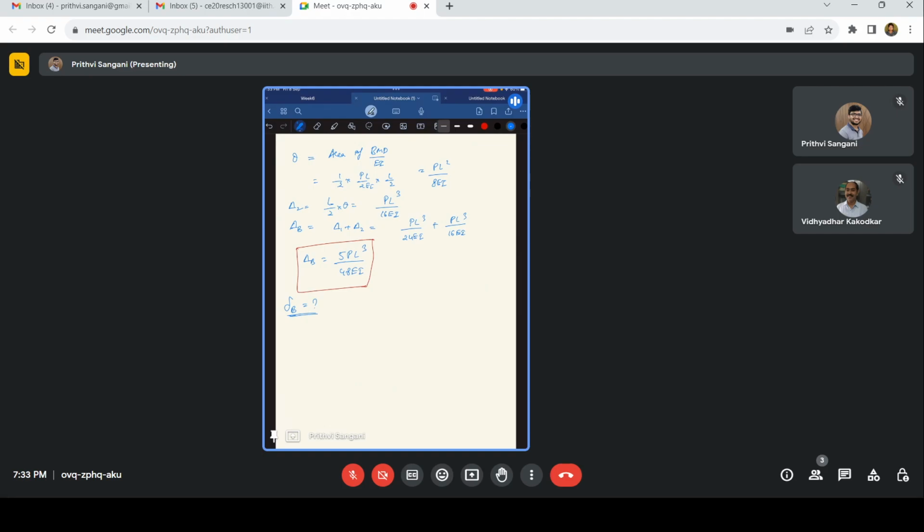The vertical reaction is entirely taken by the support A. So this is 72 kilonewtons. The horizontal reaction is 24 kilonewtons. Now we have solved for the support reactions. We'll do the same thing for the unit load. So you have 1 kilonewton acting here, which is downwards at support A.